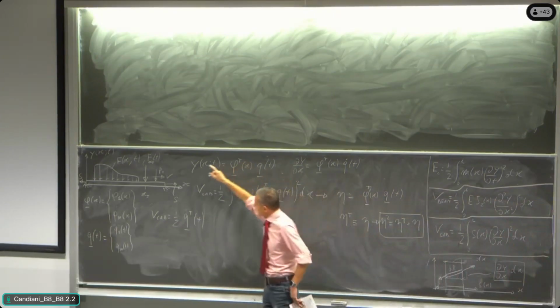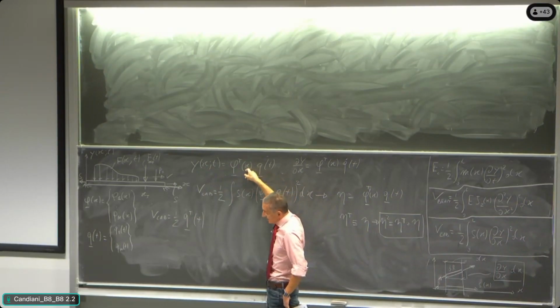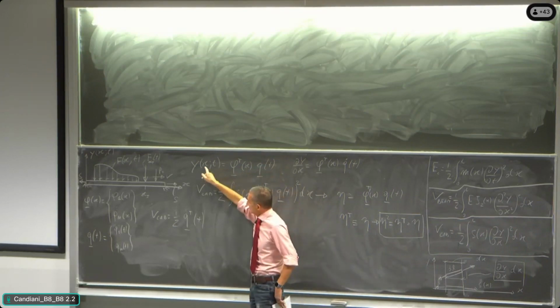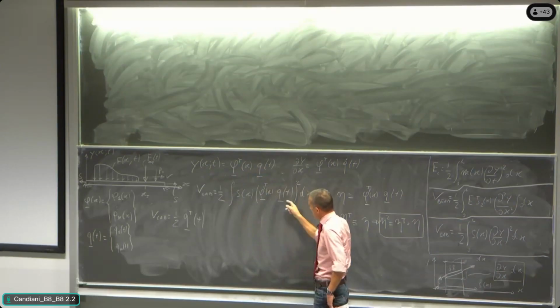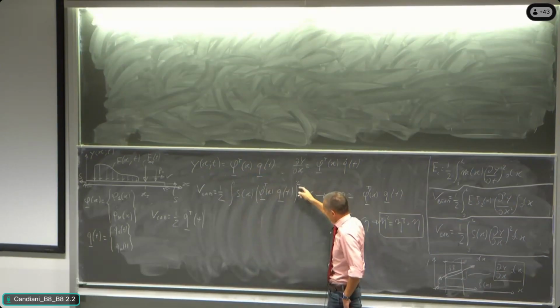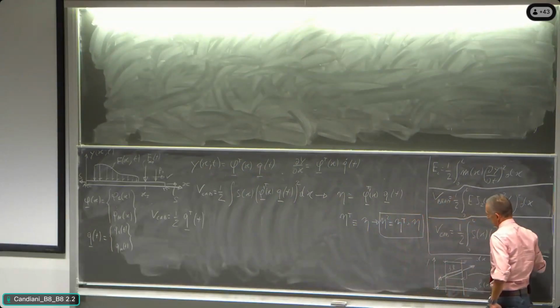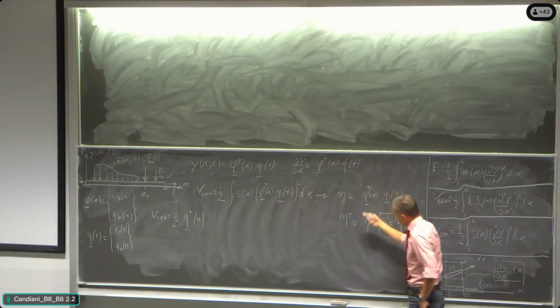So of course, y is equal to the vector of the modes, the eigenfunctions of the vibration modes, multiplying the vector of the principal coordinates. And if I take the derivative with respect to space, it makes phi first, so d phi over dx. And so we have this phi first multiplying q, that is the representation of dy over dx. We have to make the square of that, and we go back to what we said.